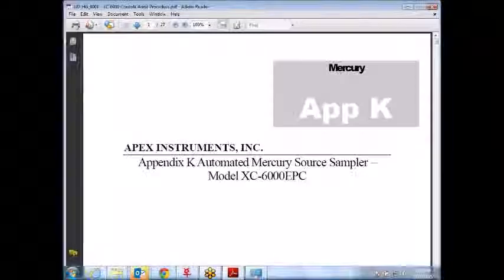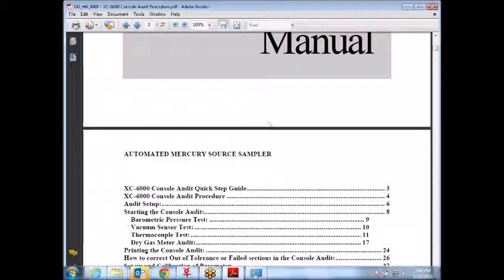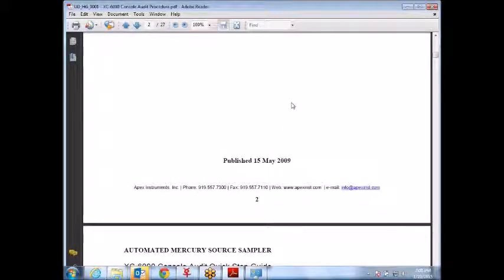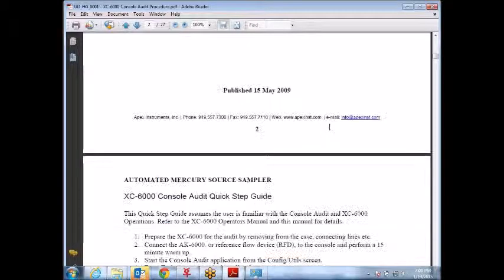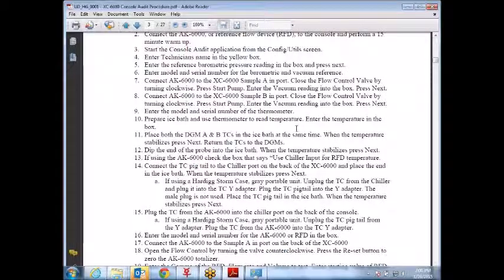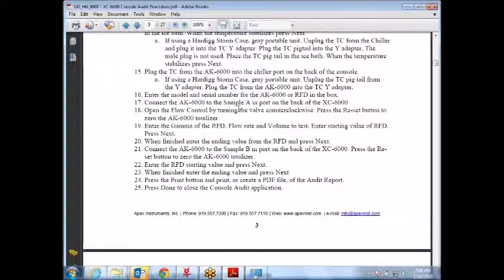Yeah, and after the upgrade, there were quite a few more connections on it than we had before. Correct. All we did is that it used to have a round Amphenol type connector, and all the TCs came out of the umbilical and went through that. Right. With part of the upgrade, we moved to just a standard jack, which is more robust and easier to troubleshoot and maintain than that Amphenol connector. You ended up having to have a special tool to pop pins and all that kind of stuff. Yeah. Originally, that's what AEP told us they wanted. We first built these things several years ago, and I think they've changed their mind too, so that's why they put that as part of the update that we did.